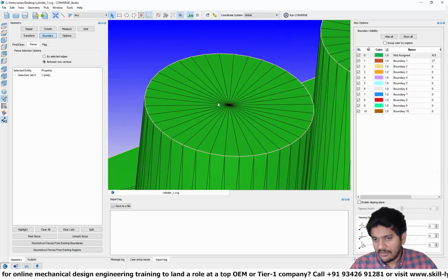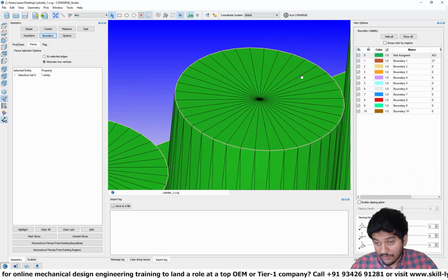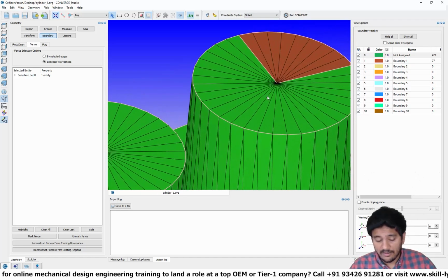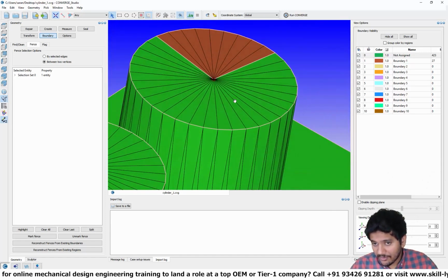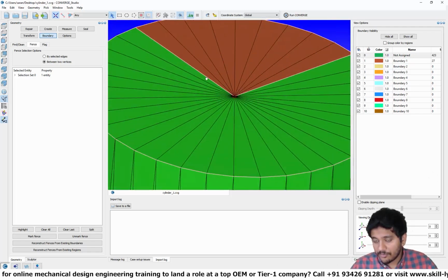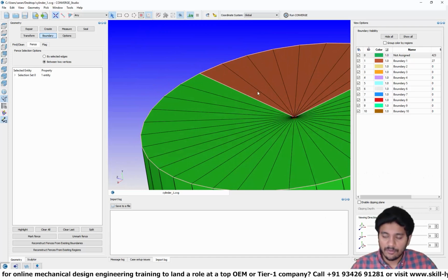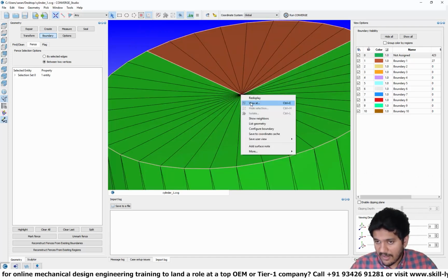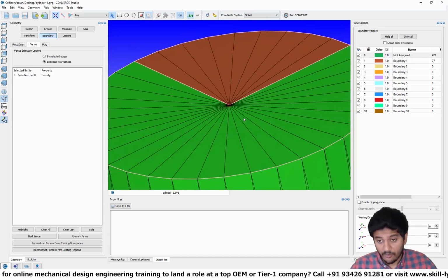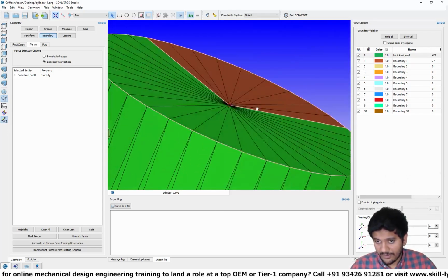So now let us say that this is my rotation center, okay, and you're still zoomed in and you want to rotate about this particular point. So I'm selecting this point, and if I try to rotate, you can see that it's becoming very hard, especially if I zoomed in, even for slight motion of my mouse, the geometry moves around a lot and that becomes very hard to control. So I can right click and click on view at, or alternatively I can use the shortcut Control E, and now rotating about this point becomes really easy. All right, so that's a handy shortcut.